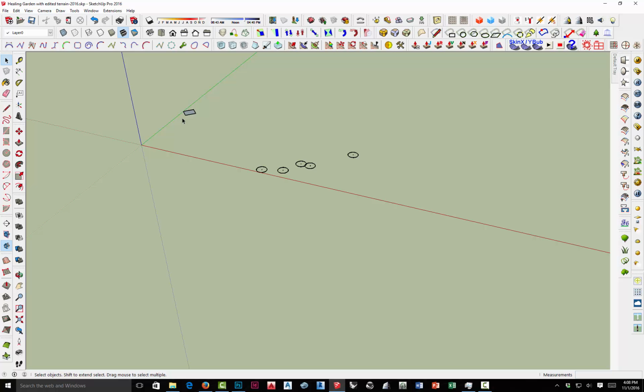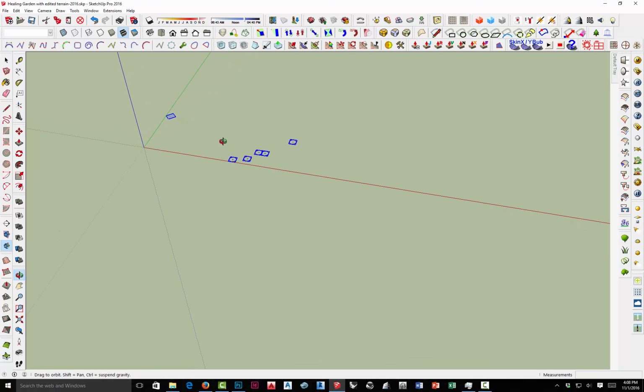What I would suggest is if you didn't do that, then go back to AutoCAD, isolate this plant layer, isolate the paving layer, and then when you type W block and enter, the first thing we do, remember, we're going to click the button that says select objects. So if you layer isolate this paving, you'll have all the other paving with it. But if you only select this and all these, and then you W block, you'll get a W block that comes into SketchUp just like this.